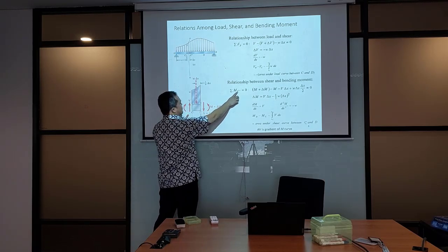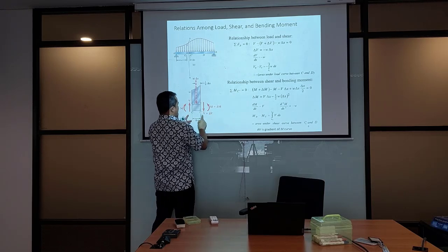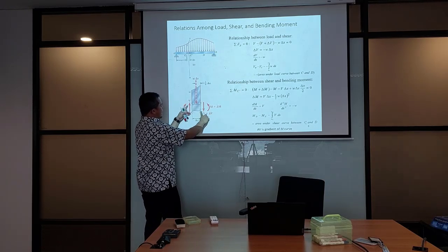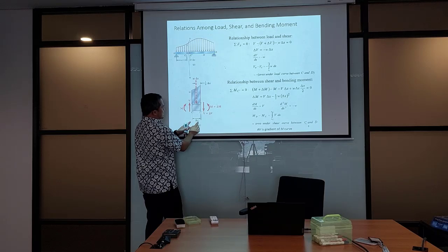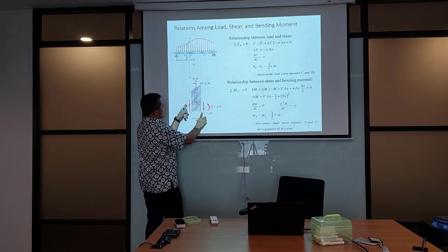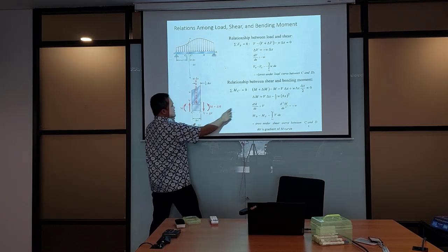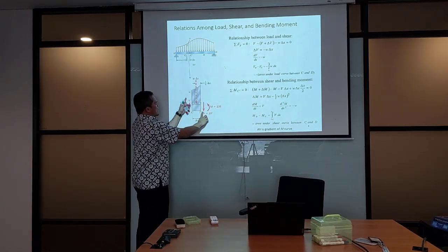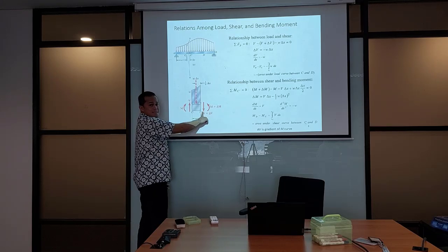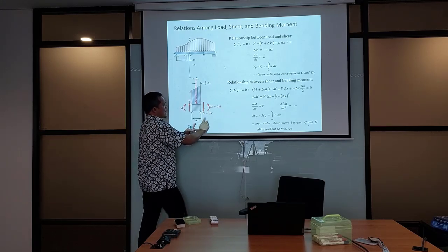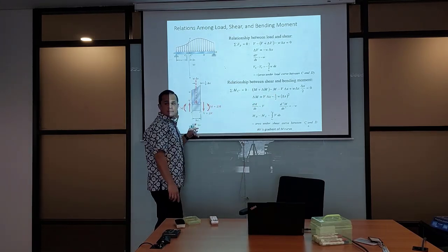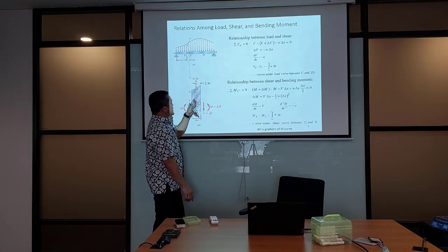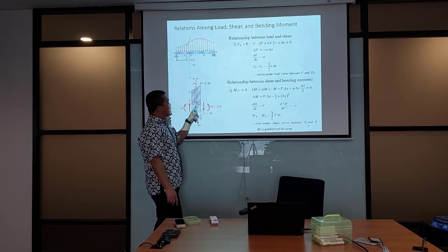It is doing the sigma M at C prime. At C prime here, V has a distance of delta X to C prime. Therefore, the moment because of V is V times delta X. From C prime, V is creating a clockwise moment. Therefore, V times delta X is minus. And then what is remaining is the dashed line, the W.